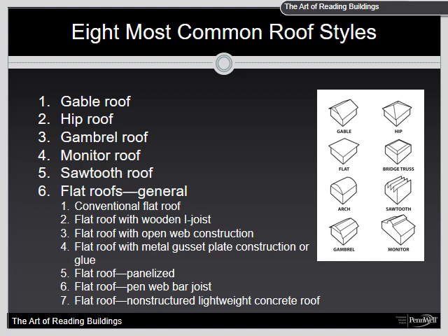The large open areas in monitor buildings will enhance the horizontal and vertical extension of fire and smoke. Consider the feasibility of using the upper window eaves in monitor buildings for vertical ventilation. A diverse interior fire load can be expected in monitor roof buildings and vary widely from farm animals, hay, and RV storage to offices and multiple commercial occupancies.